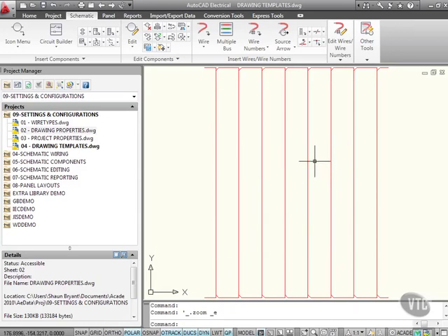Now before we do that, I'm going to change a variable in AutoCAD. Now I've got my dynamic input switched on. I tend to use it all the time. I type the word startup, S-T-A-R-T-U-P, all one word, and press enter. Now the default setting for the AutoCAD variable startup is 0, which means that the startup dialog box does not appear when you click on new or type in new for a new drawing.